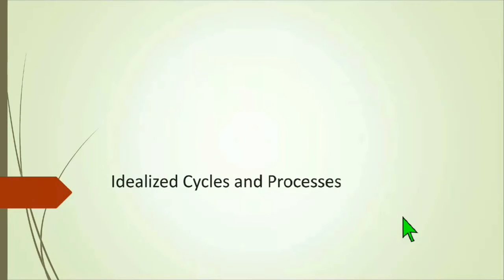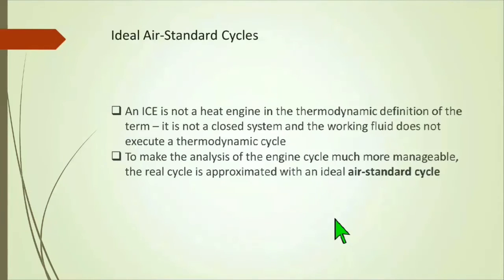This particular lecture is about idealized cycles and processes. Ideal air standard cycles. An IC engine is not a heat engine in the thermodynamic definition of the term. It is not a closed system and the working fluid does not execute a thermodynamic cycle. To make the analysis of the engine cycle much more manageable, the real cycle is approximated with an ideal air standard cycle.